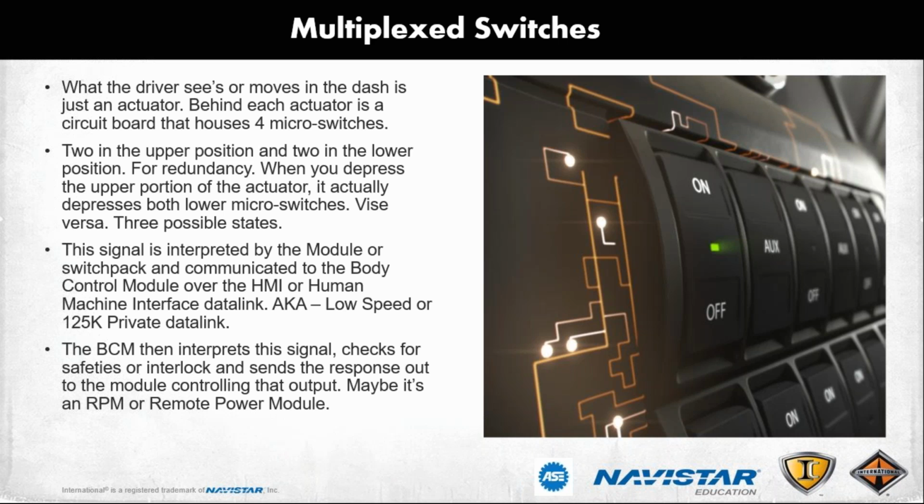These are criteria that must be met, and you can make it, like I said before, lock to a park brake on or off, or certain air pressures, certain gears, certain road speeds, a lot of different factors that can be programmed into that interlock to either prevent or enable an output from coming on.